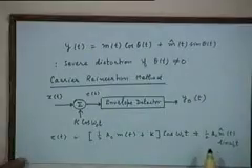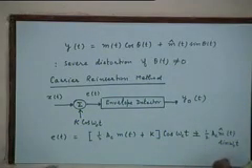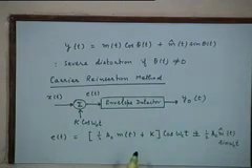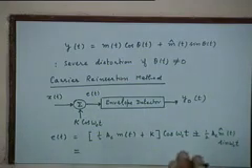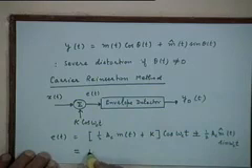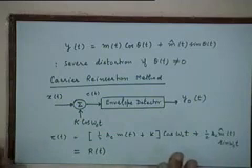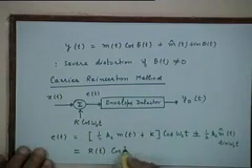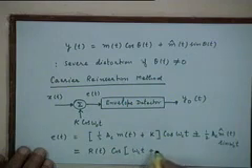Now, one of the advantages of this representation is that you can easily identify what the envelope of the signal will be by writing this expression. If you remember the definition of the envelope, the basic definition was that it is a trace of the positive peaks of the carrier, right? So to understand how we can identify the envelope, one can rewrite this as an amplitude part R(t), which is always positive, into cosine omega ct plus a phase part theta(t).